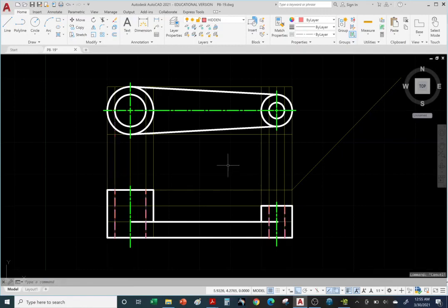Okay, let me hit escape to exit. All right, so for those of you that are wondering, hey, how do you change the gaps between the dashes? LTS, right? LTS. Not as easy as 1, 2, 3. So we can type in LTS if you want to play around with it. Maybe you want to increase the LTS. Go to the command line, LTS. And again, you wait till the very end.